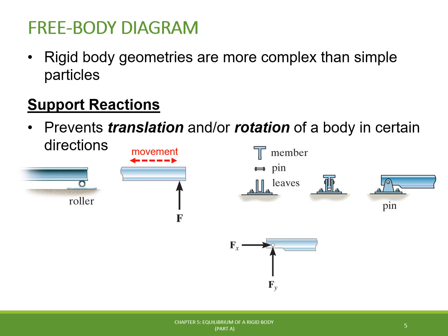As a result, the pin connection can prevent both vertical and horizontal translation, and the two reactive forces Fx and Fy appear in the support. However, the beam is still free to rotate about the pin axis in any direction angle phi.